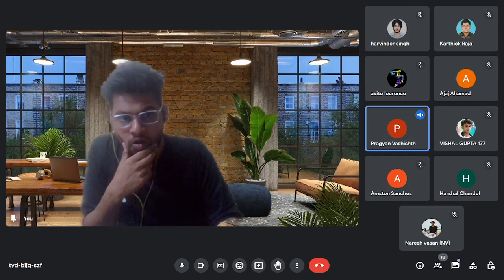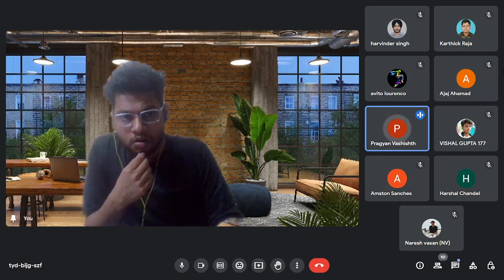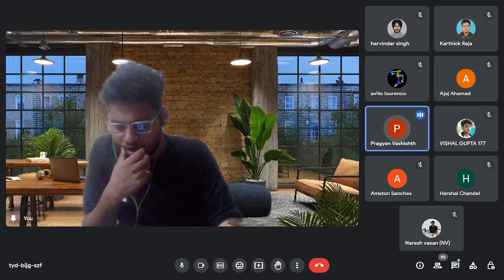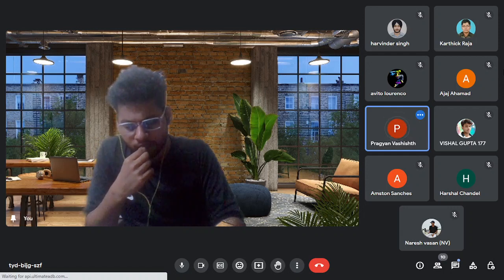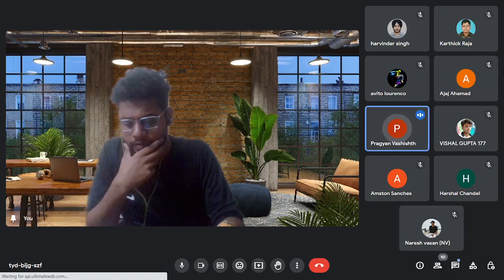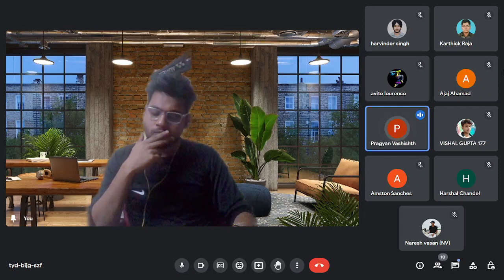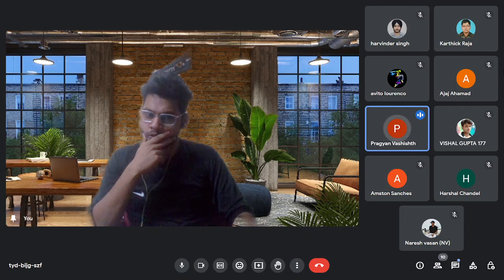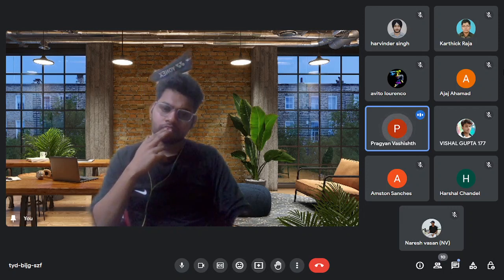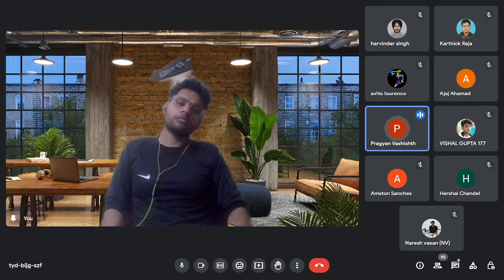And the working is as follows. When we place the probe on our material, it could be any type of material, like ferromagnetic, non-metal, anything. Then the probe generates high pitched mechanical sound waves, which travel through the test object and get reflected back either at the bottom of the test subject, or at a crack or porosity or any cold shut there might be in the test subject. And when the sound waves return to the probe, the probe sends the signal.